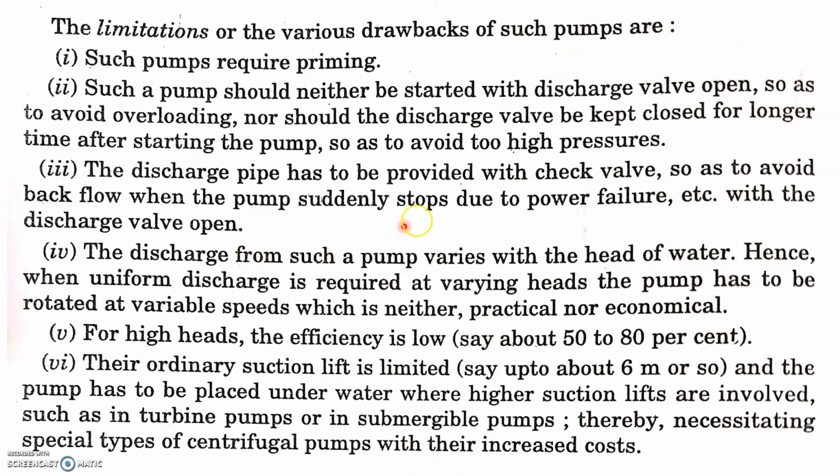Next one, some of the disadvantages. Some of the disadvantages here are, there is a priming requirement. One more thing, when you start up a pump, the valve should always be open. There should not be any overloading. And when you start up the pump, the valve should not be closed for a longer time, because there is high pressure, and there will be breakage in the pump or in the distribution system.